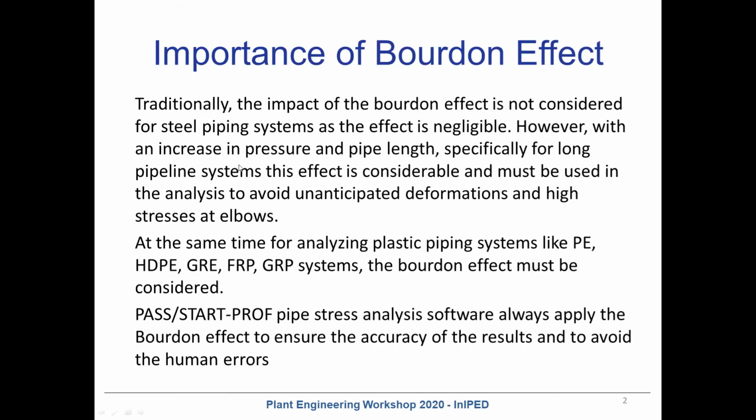Traditionally, the impact of Bourdon effect is not considered for the steel piping systems because it is not very important. However, for high pressure piping systems or for very long pipelines or for non-metallic piping systems like high density polyethylene, GRE, GRP, FRP piping systems, the Bourdon effect is very important and it should be taken into account during the pipe stress analysis.